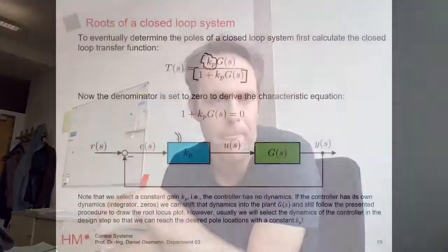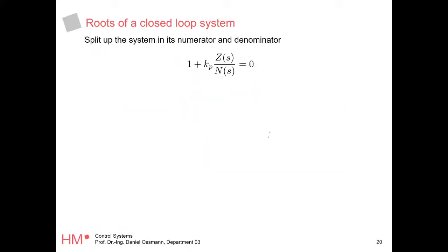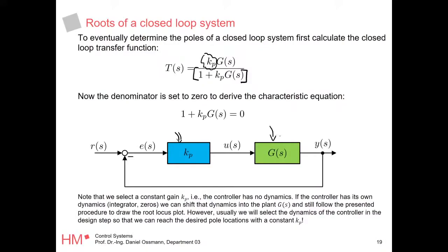You just need to move it to the system, because you again want to know which points you reach with proportional gain. Otherwise, a two-dimensional working style would not work, because with a PID controller you would need a three-dimensional graph. So you restrict yourself to this one controller gain, and all the other elements you plug in here.